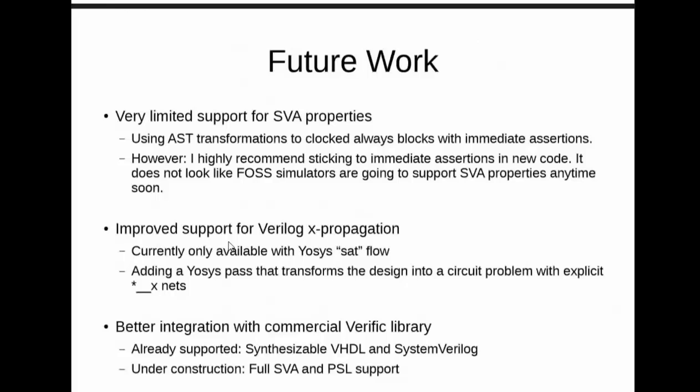Another thing is improved support for X propagation. Within Yosys, I can actually do formal verification of things that involve X propagation, but this is not yet integrated with SymbiYosys, and it's not available with all solvers now. So this is something else that I'm working on. The last thing on this list is better integration with the Verific library.